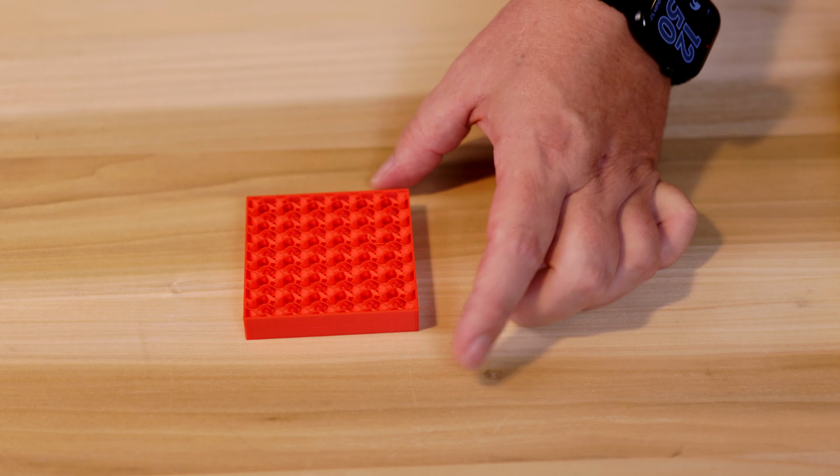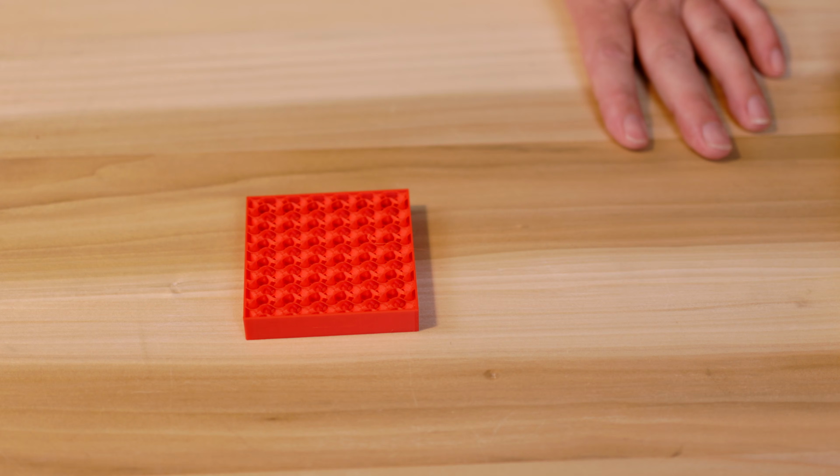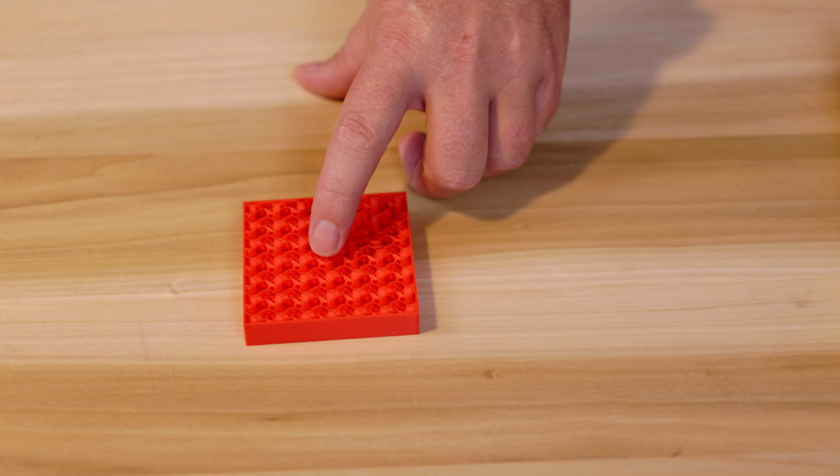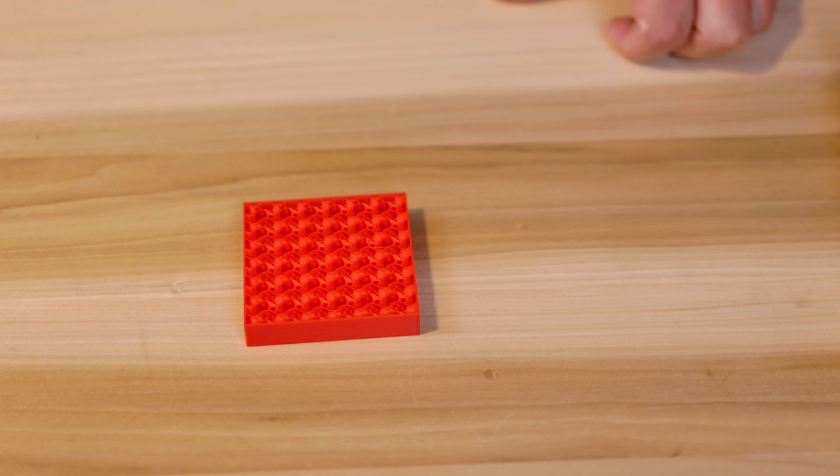And the use case for this is parts that need strength and flexibility. And the pro here is isotropic strength. And the con is going to be longer print times, and it does affect the print time, but not so much the amount of material. On the printing tip, monitor first few layers to ensure proper adhesion due to the complexity of the pattern here.